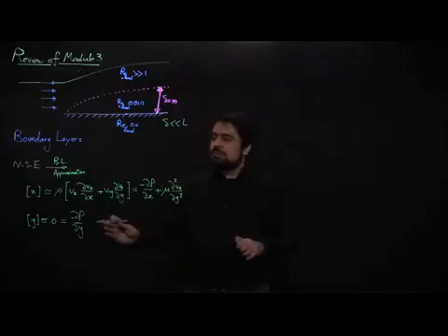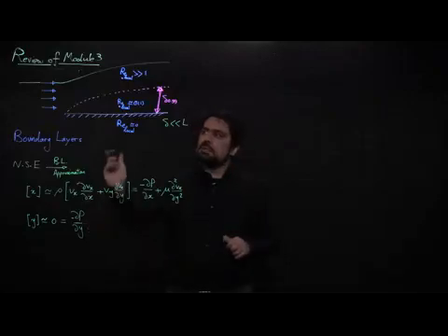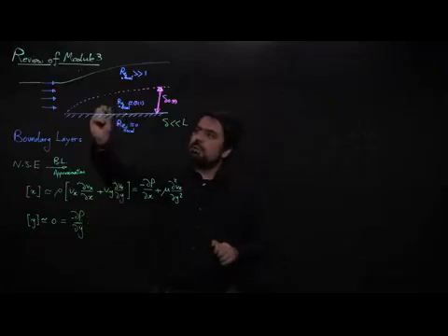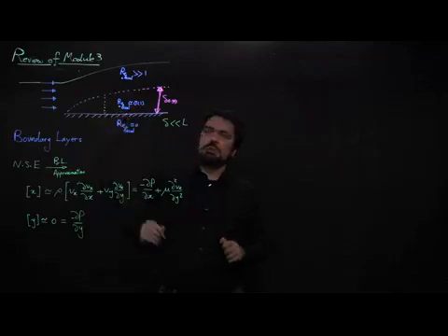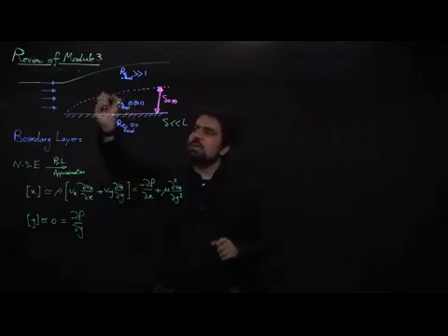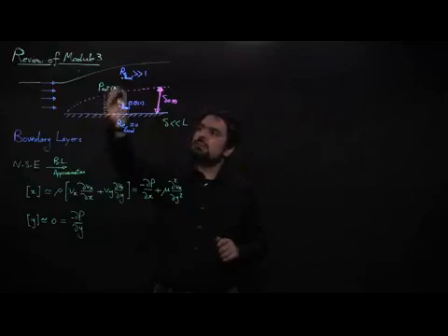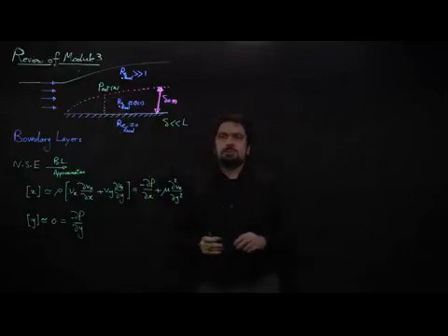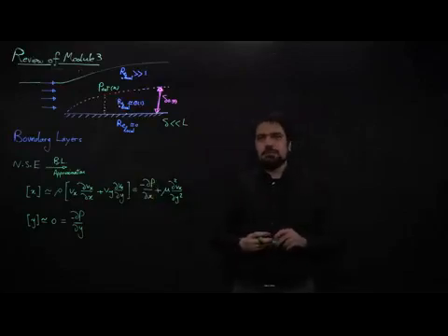What this equation really tells us is that pressure inside the boundary layer at a fixed x is not changing vertically with y. In other words, the pressure inside the boundary layer will be set by the pressure distribution outside the boundary layer as a function of x.